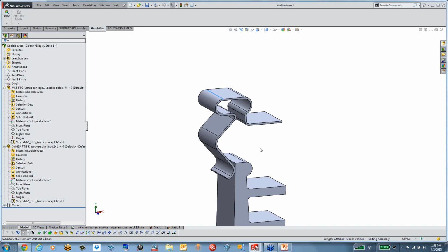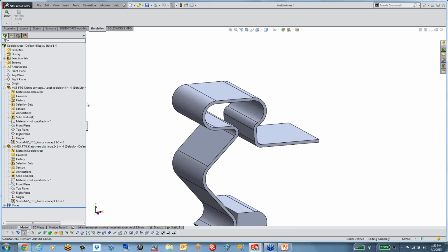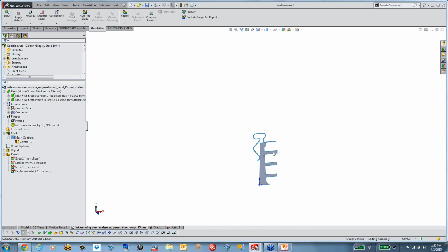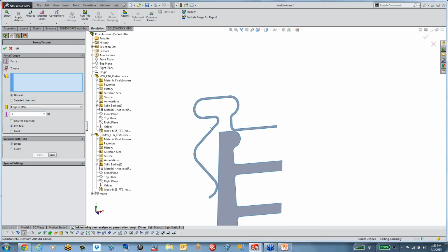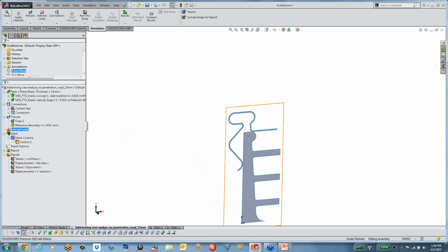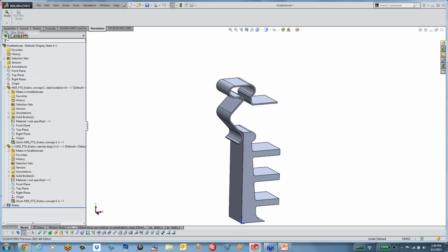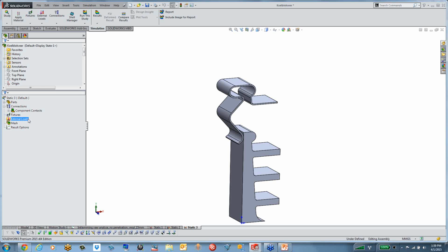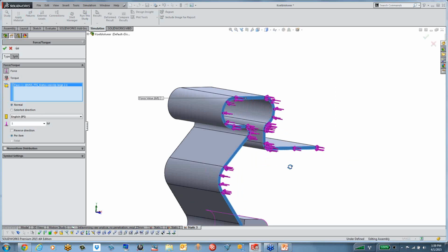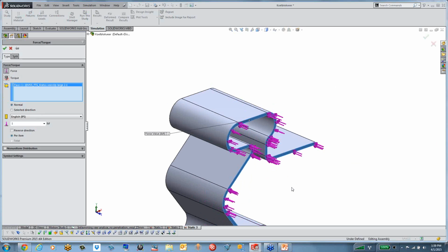But then also the loads and your restraints have to act around the cross section. So here, for example, if I had something, let's say the load is actually acting something like this. So let's go ahead and apply, just to give you an idea, proof of concept. So if the load was, okay, this is already a 2D section. So let's go ahead and create a new simulation study on the full 3D model. So let's say the load was acting in plane, or perpendicular to the cross section.